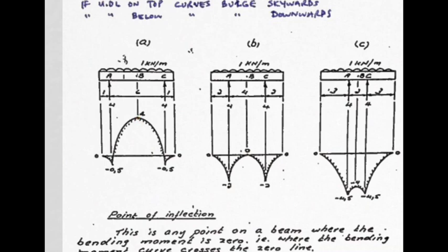Now as you can see, as the supports came in from each end, so this curve descended until it was way down here. Now if we want that bending moment to be numerically as small as possible, in other words, to cause the least bending on our beam, whatever the biggest minus number is, it had better be equal to the biggest plus number.